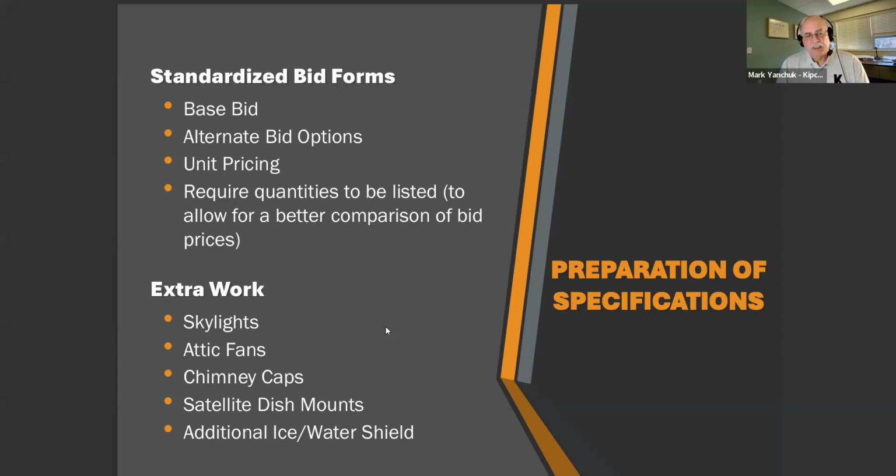And in this way, you'll have some level of protection in the attic from degradation of the shingles. We also recommend blocking off the exhaust vent on the ridge within 5 feet of any attic fans to help prevent some short circuiting when they do come on.